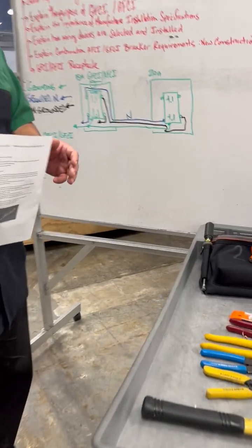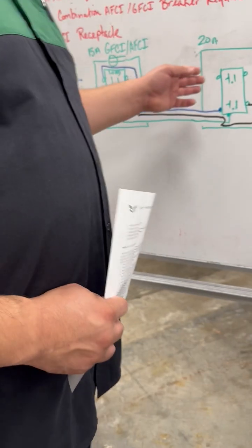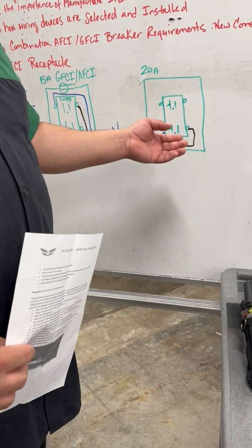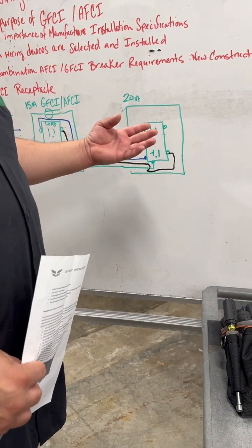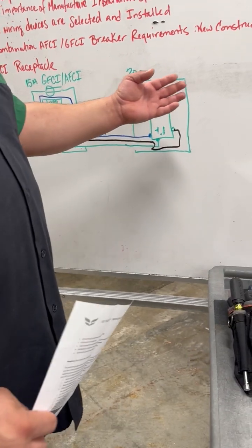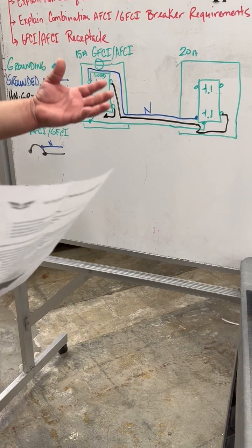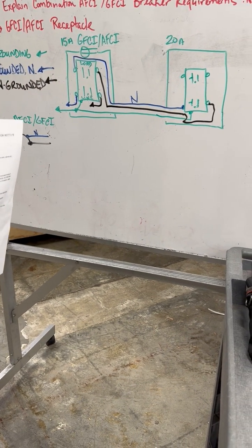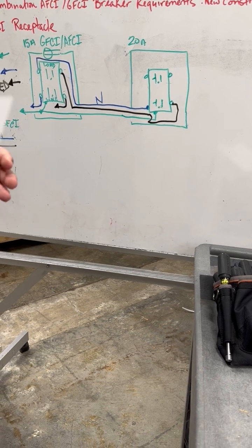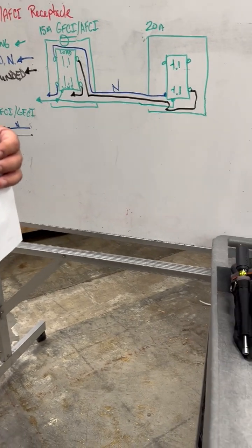We want to make sure that we have the understanding that this is a regular standard receptacle, that we're going to have a multiple of 3 in the circuit. But like I said, I gave my class a little calculation based on the NEC's recommendation of applying 180 volt amps to each receptacle in the circuit.